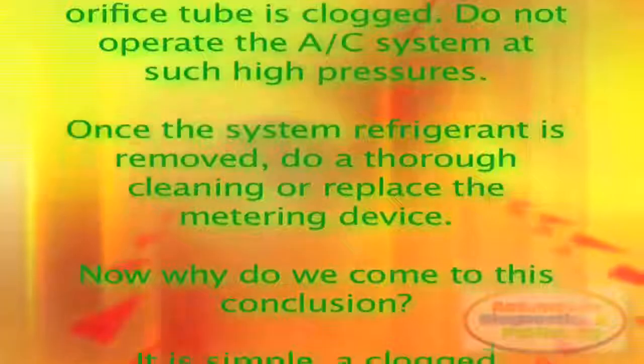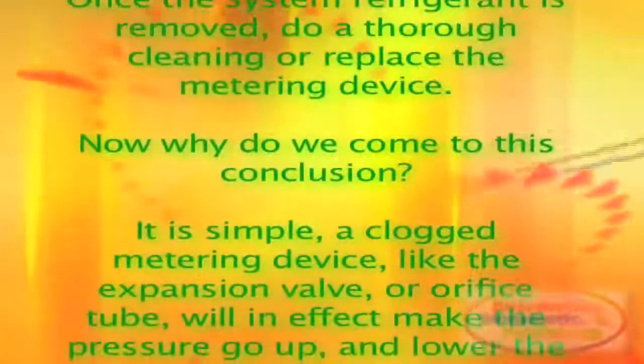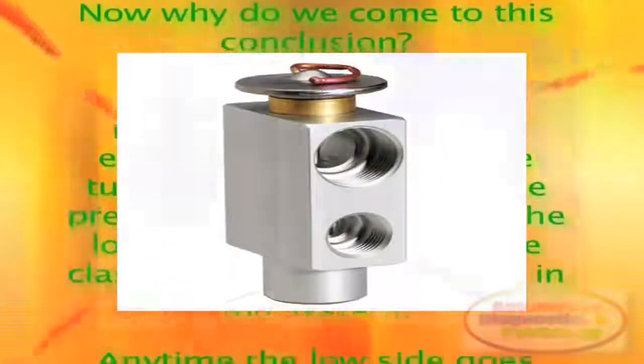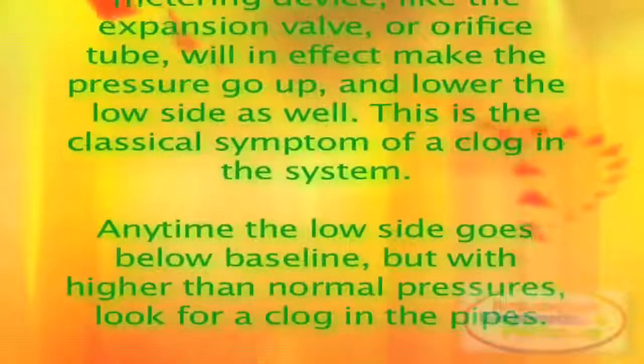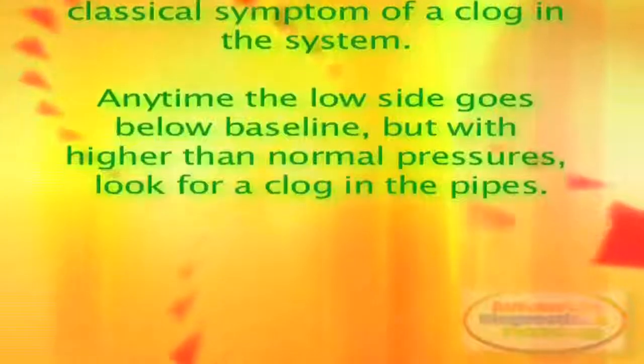Now why do we come to this conclusion? It is simple. A clogged metering device, like the expansion valve or orifice tube, will in effect make the pressure go up, and lower the low side as well. This is the classical symptom of a clog in the system. Anytime the low side goes below baseline, but with higher than normal pressures, look for a clog in the pipes.